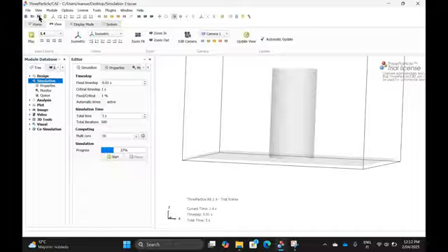At some point it suddenly gets unstable. And that's probably one thing with spheres. The critical time step works quite well. As soon as you leave spheres towards donuts, bottles, objects like boxes, cylinders, capsules, something like that, the critical time step gets to be a big problem. So this is too high. We'll go down even more.